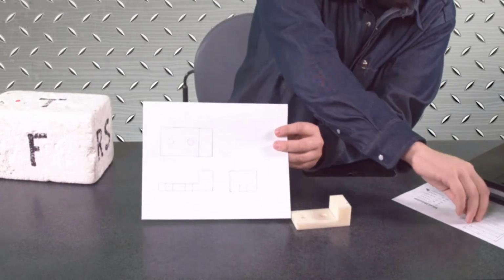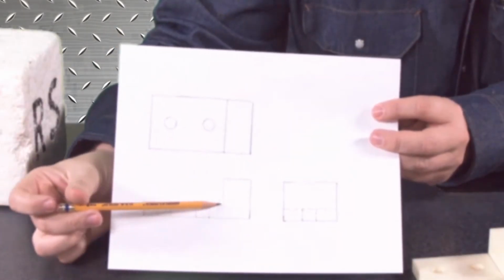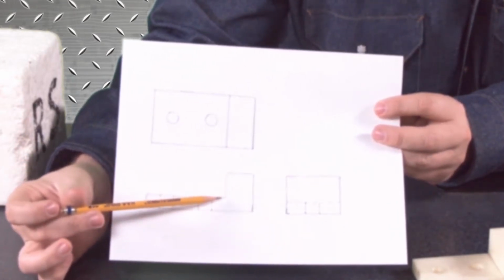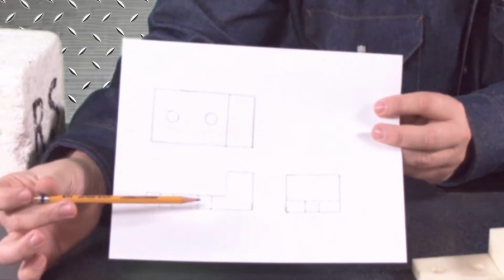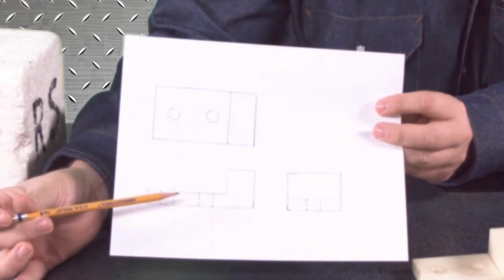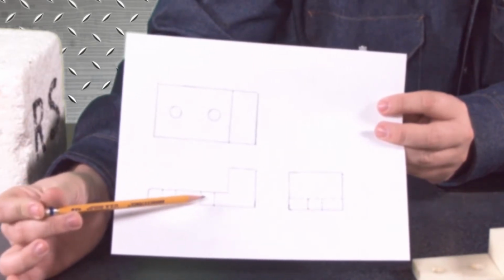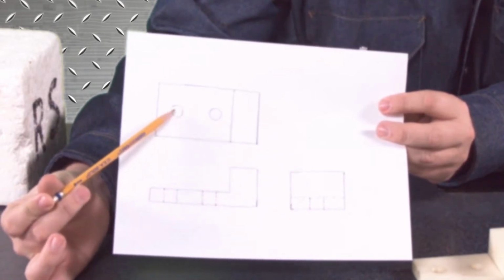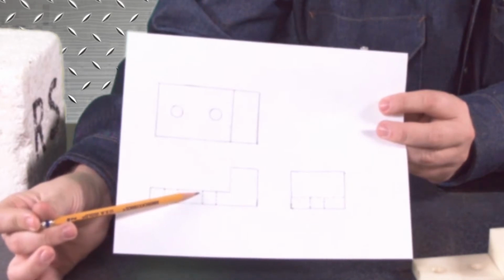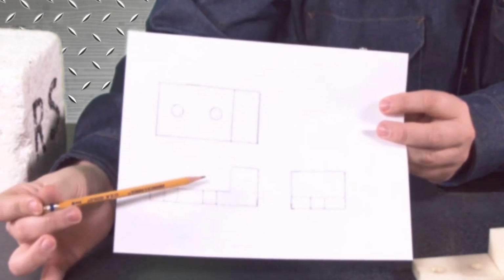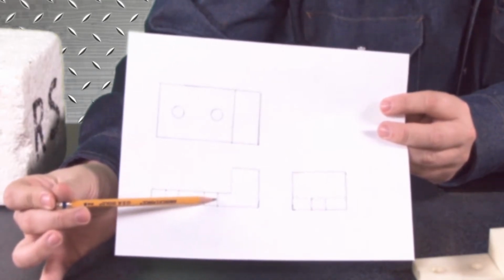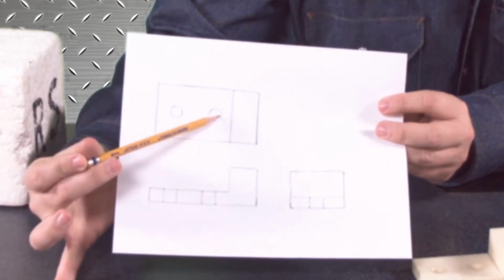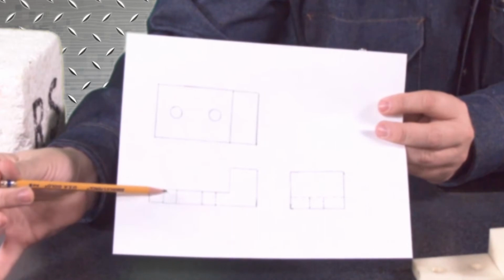So you'd have, this is your front side view, and all of these solid thicker lines here, these are all object lines. From this view, these are all visible edges of the part, all right? Now these little dashed lines right here, these are our hidden lines. Because, as you can see from our top view, there are holes in this part. You can't see it from the front view. So to represent those holes that are bored through or drilled through, you can actually see the hidden lines. And this represents the edges of these holes there and there. And that's what those hidden lines are showing us.